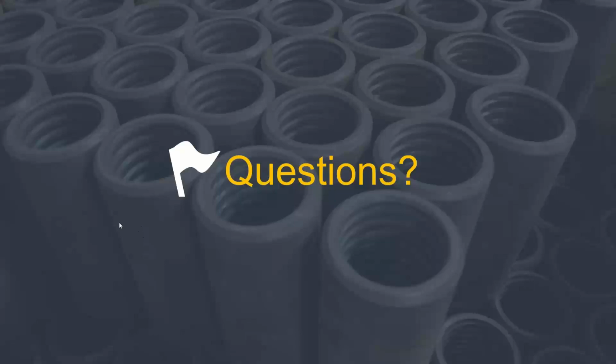Right. So obviously grade beams will be a great way to compensate for 2 piles in a pile cap, because you're going to brace it in one direction and the grade beam will brace it in the other. And remember, this is just what the IBC is suggesting you do: have 3 piles or 2 with grade beams. I have seen very lightly loaded warehouse structures end up with only 1 pile per cap, and it's not the most stable condition and doesn't necessarily align with the IBC, but it is doable in some situations to only use 1 pile per cap.